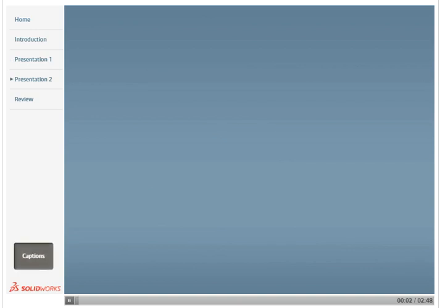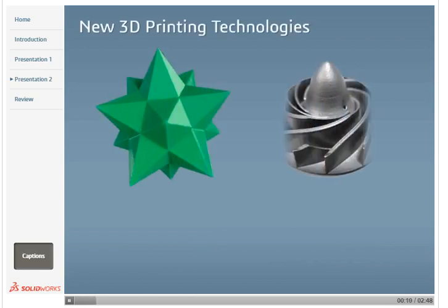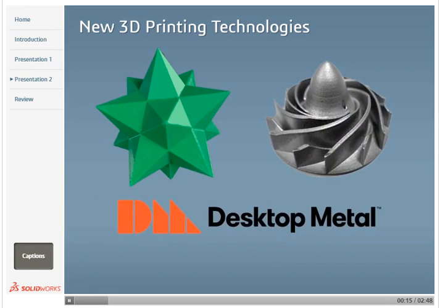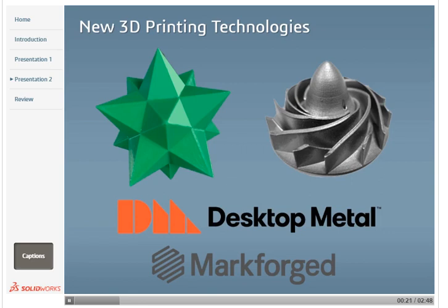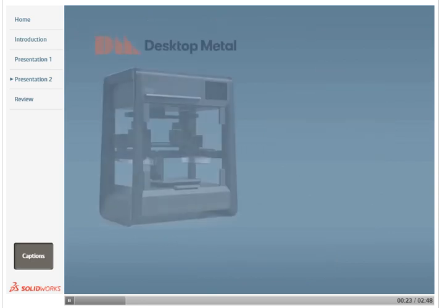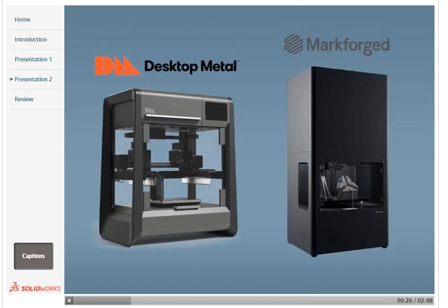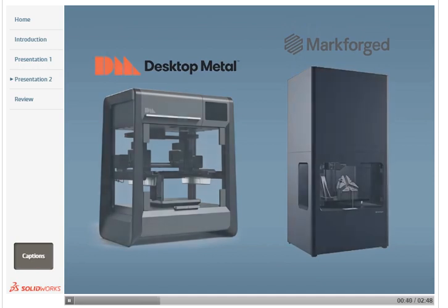As 3D printing continues to be adopted by companies and individuals, new technologies are becoming mainstream. 3D printing isn't restricted to just plastics, but has made its way into the world of printing metal. Metal printers from companies like Desktop Metal and Markforged are allowing companies to print final design parts at the lowest costs possible. With these machines, different types of metal materials can be printed, but all will require some sort of post-printing curing to fully harden the part. The ease of use of the machines, along with the easy-to-use software programs, are allowing for this technology to gain momentum at a very fast pace.